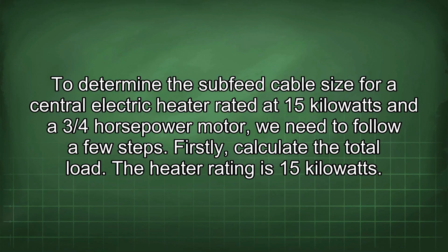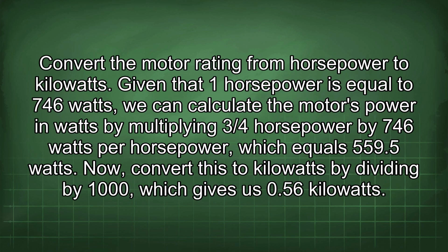To determine the subfeed cable size for a central electric heater rated at 15 kilowatts and a 3/4 horsepower motor, we need to follow a few steps. Firstly, calculate the total load. The heater rating is 15 kilowatts. Convert the motor rating from horsepower to kilowatts.